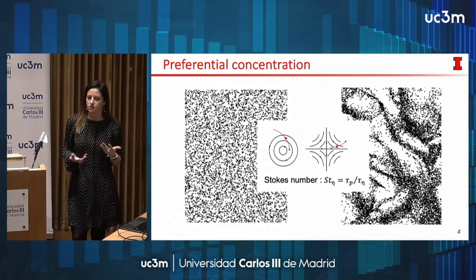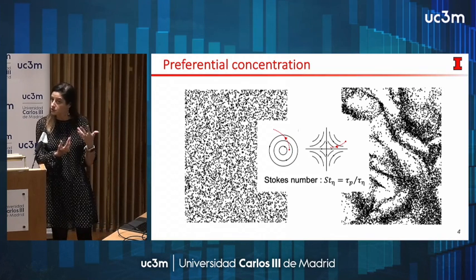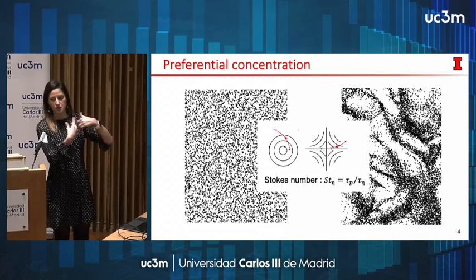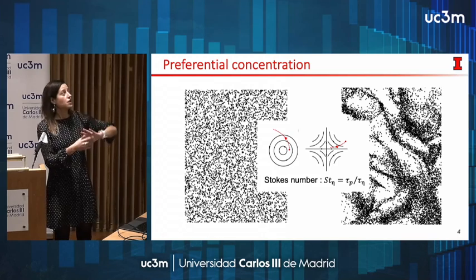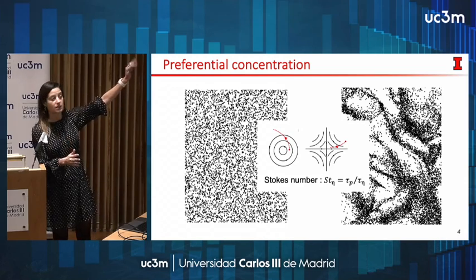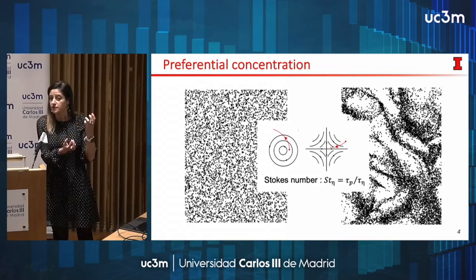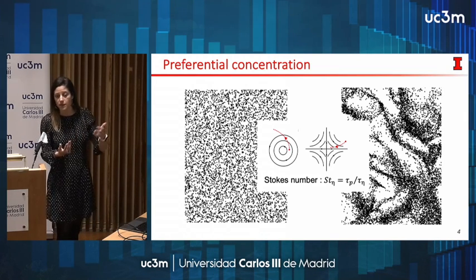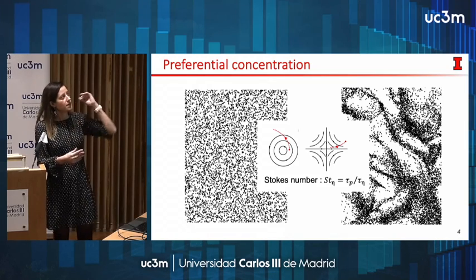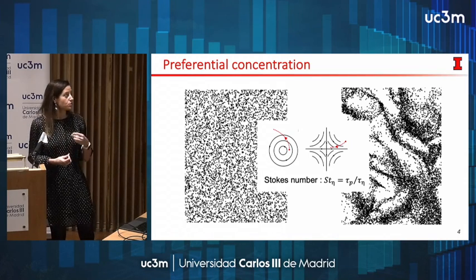There we are in a situation where we have a tracer. These are the particles that you want if you do particle image velocimetry, for instance, those of you that do experiments. You want your particles to follow exactly the flow. So if you put them in there, filling all the space, they are going to exhibit a random uniform distribution, right? So like on the left. If your particles, imagine, are very big, they are ballistic at the end of the day. They don't really care about what the flow is doing, and you will end up with the same random distribution.